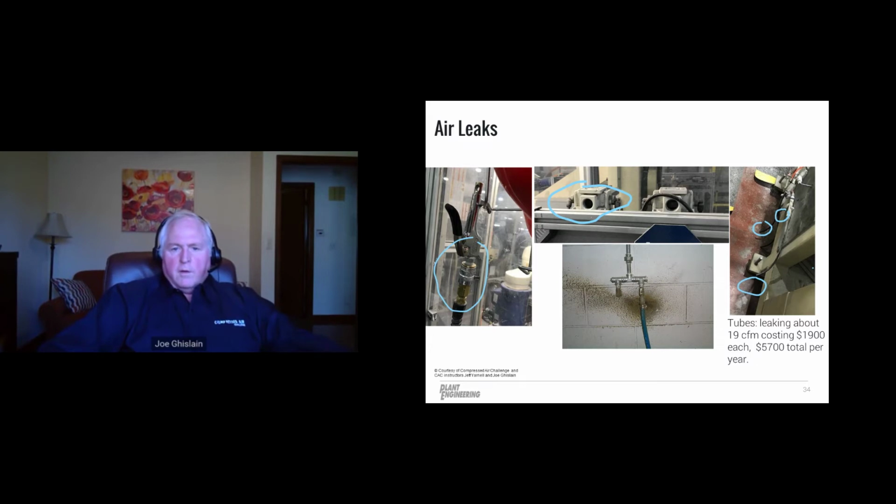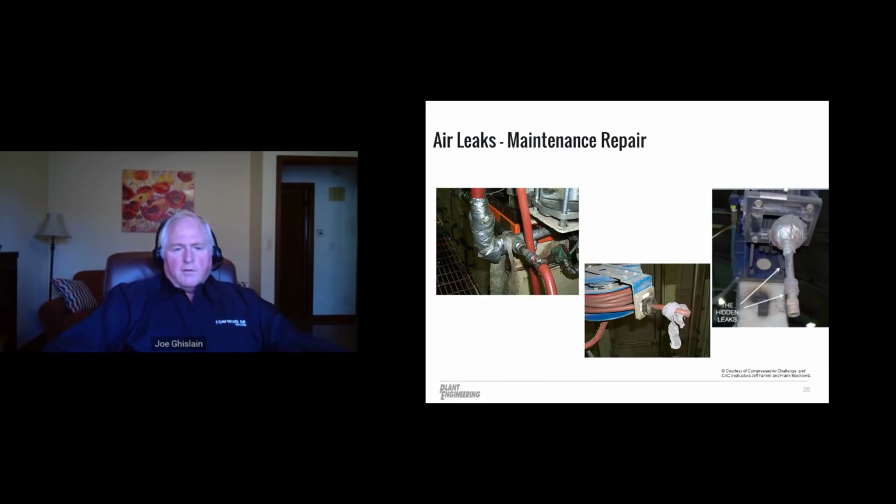Of course, the one down in the middle with that nice white wall where you see the oil against it, you don't need ultrasonic leak detection on an oil system if it leaks that bad. You can pretty well find that one. That's a visual. You can see in that bottom corner those tubes that were there, I did a calculation of it, and they were costing $1,900 per year. And again, $57 per year for total. It's a large cost that can be in small leaks that you're not even aware of or not even looking at. And of course, we repair these air leaks, and sometimes we do it on the fly.